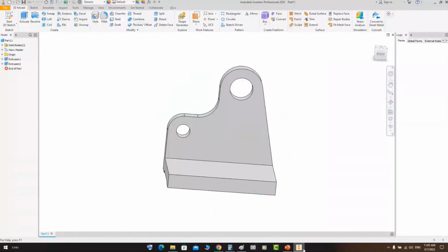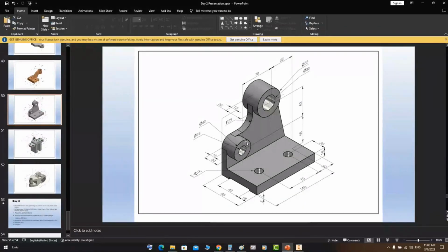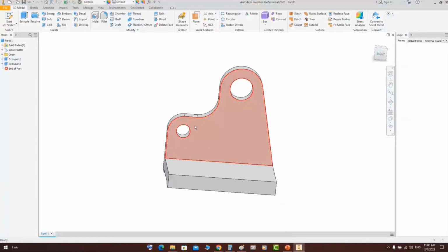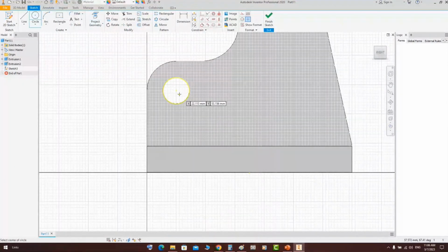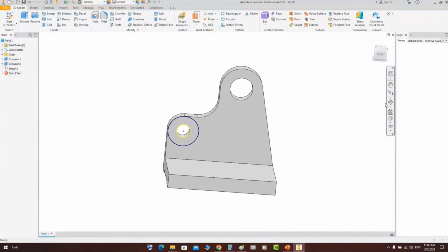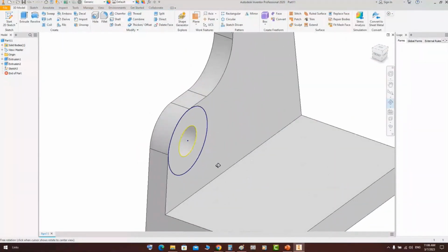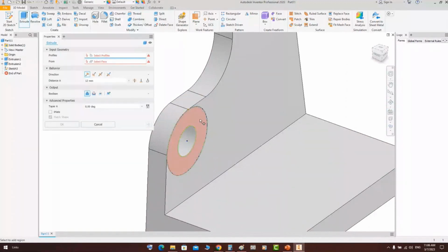Okay. Now we need to make another extra pieces, one of them for this small one with 30 millimeters extrude from the end. So if we select this surface and create a new sketch, you can project this circle and create a new circle for the outside, and make this circle, by the way, located on that point, so automatically it will take the same diameter of the circle here. If you click finish, now you have this circle, and you can make a separate extrude for this one.